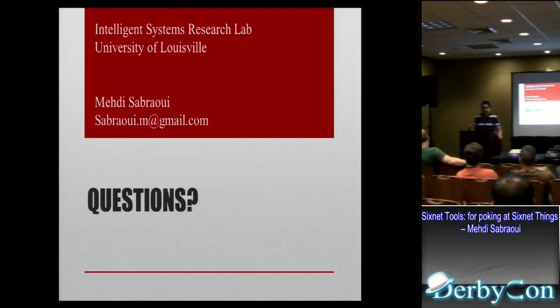By manipulating the file system. That information is in there. There are a few other built-in tools in the tool set to figure that out. It'll give you the firmware version of the device. You can pump out the ladder logic of it too. And so far, I've only been able to test it on this one specific RTU, but it is a universal protocol, and so it'll run on any device that supports that protocol.